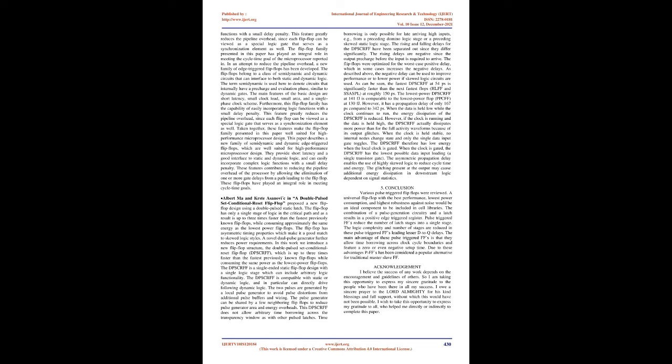a new family of edge-triggered flip-flops has been developed. The flip-flops belong to a class of semi-dynamic and dynamic circuits that can interface to both static and dynamic logic. The term semi-dynamic is used here to denote circuits that internally have a precharge and evaluation phase, similar to dynamic gates. The main features of the basic design are short latency, small clock load, small area, and a single-phase clock scheme. Furthermore, this flip-flop family has the capability of easily incorporating logic functions with a small delay penalty. This feature greatly reduces the pipeline overhead, since each flip-flop can be viewed as a special logic gate that serves as a synchronization element as well.